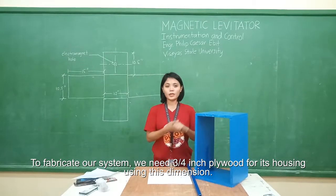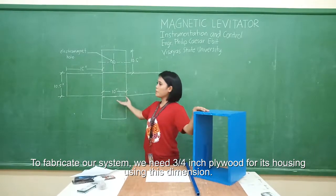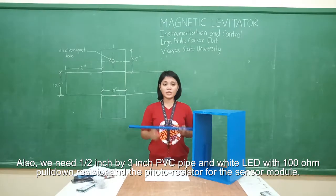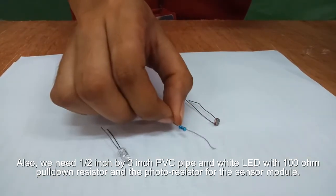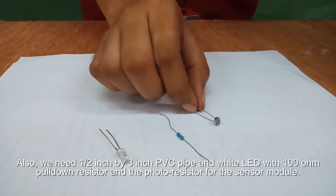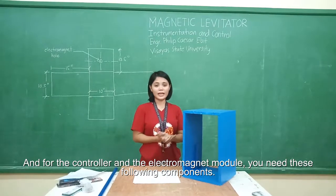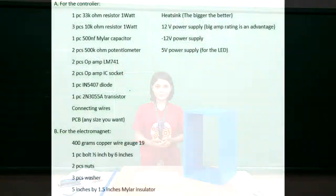For our system, we need 3/4-inch plywood for each housing using this dimension. And also, we need a 1/2 inch by 3 inches PVC pipe and a white LED with a 100 ohm holding resistor and a photoresistor for the sensor module. And for the controller and the electromagnet module, you need these following components.